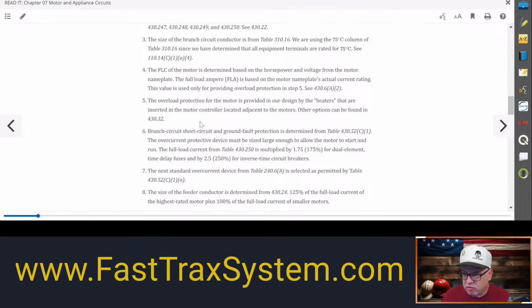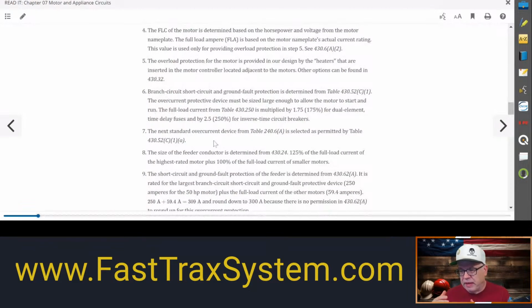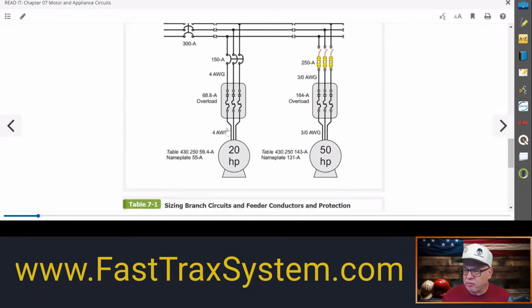At the end of the day, you're just following what it tells you to use. But in real world scenarios, you must pay attention to whatever the nameplate says and whether the service factor or the temperature rise is in play. In our case, just for our example today, we're going to say that the service factor is higher than 1.15. So we're going to be using the 125%.